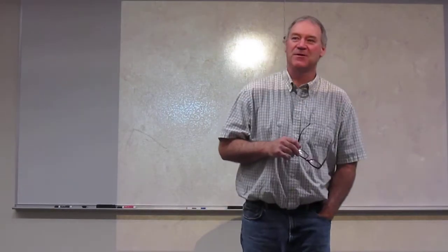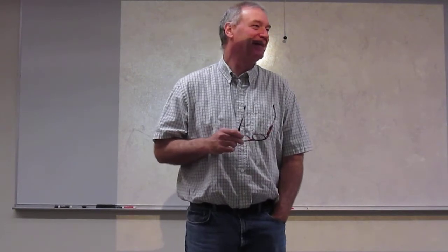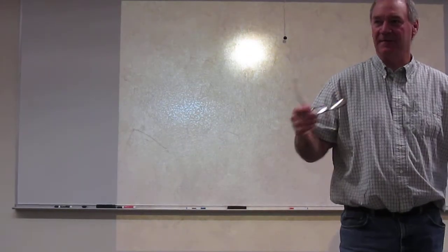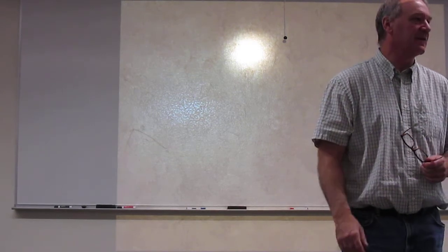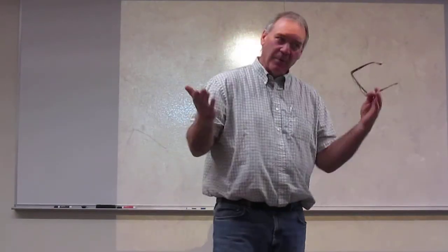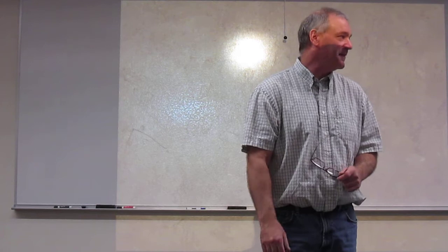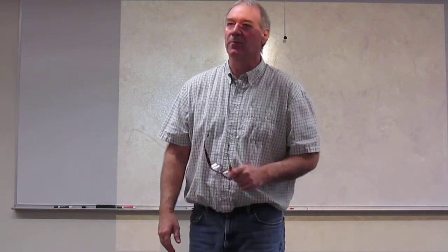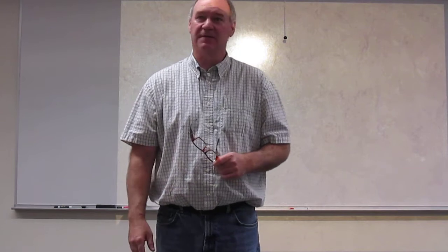Does anybody know what our nominal size is in here? Generally, what have I asked you to memorize as far as fractions and decimals? Every 16th? Okay, if I was working in this environment, we would probably use 16th as our nominal size. Now, if you go to a machine shop that has some resources, not a great, maybe you're going to a 32nd, and that is their nominal size. Usually we look at it as the base unit as a fraction. There are places that will work 1/128th, that's their nominal size.